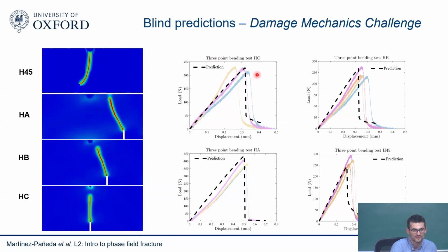So since this is a 3D printed derivative, the porosity, so yeah, I think that probably since they follow the same printing protocol, the porosity is the same in all of them. So it would have been a challenge for us if they didn't give us a single test. They gave us one test. If they didn't give a single test and we say we are 3D printing this material, let's say Portland cement, then we will have data for Portland cement maybe in the absence of 3D printing, conventional methods. So we'll have to extrapolate from our toughness and strength to porosity influence on toughness and strength. Since they gave us one and they printed all with the same method, then we could calibrate strength and toughness with one, and then we could predict the other ones.